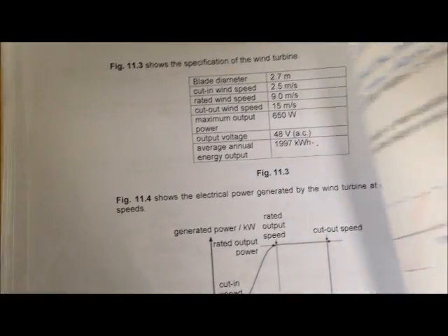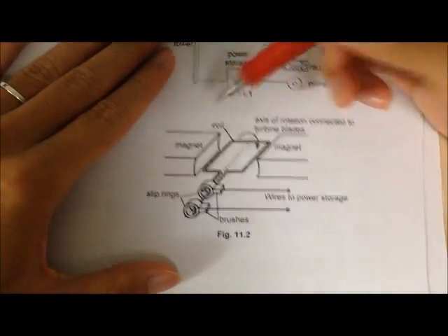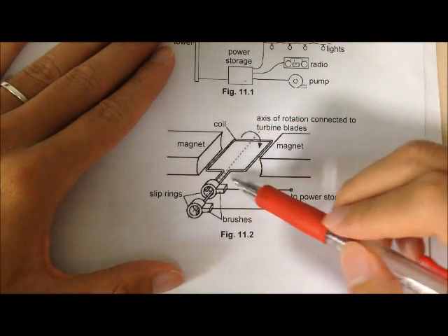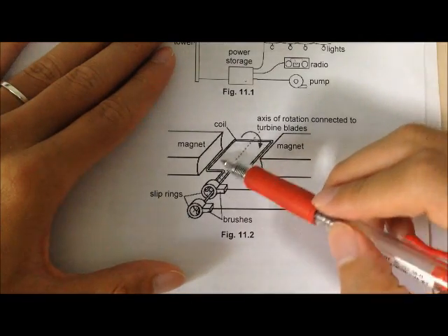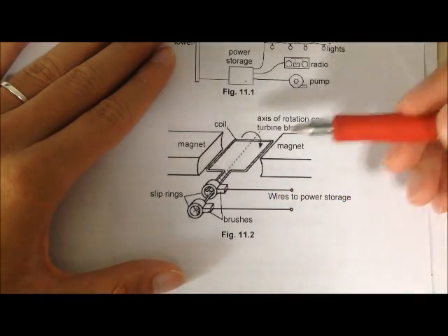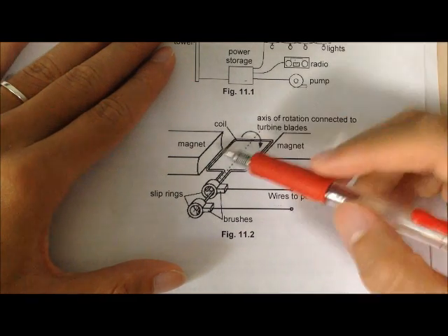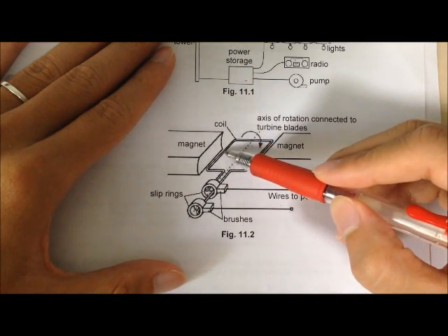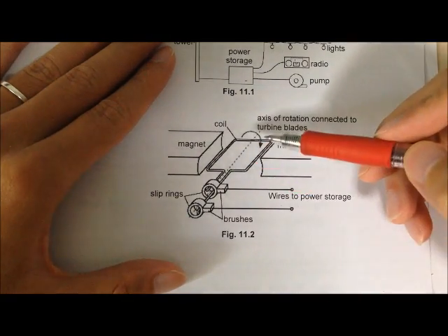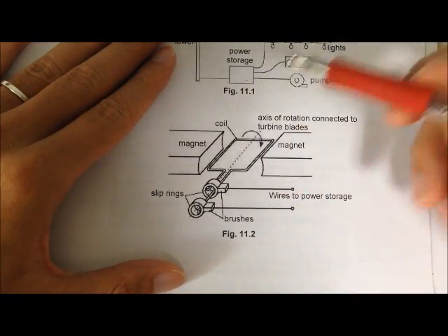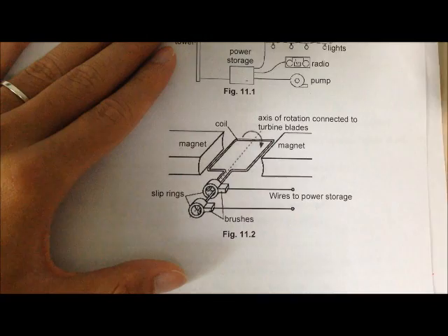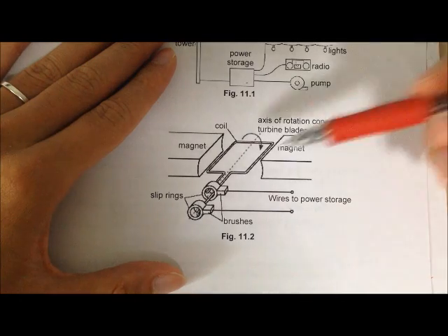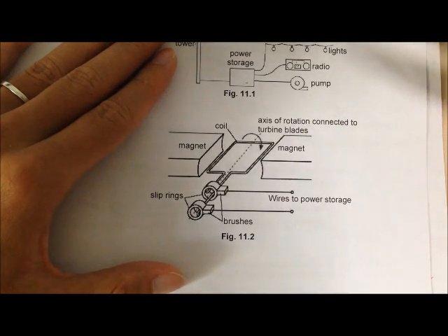So if I refer you to this diagram, what happens is that between the permanent magnet there will be one magnetic field, and as you rotate this coil, the coil itself from the induced current will actually produce its own magnetic field. So the magnetic field produced by the induced current here will actually want to oppose this movement, and your generator can only generate current if you provide enough work done to overcome this resistive force. Okay, so that is the explanation.